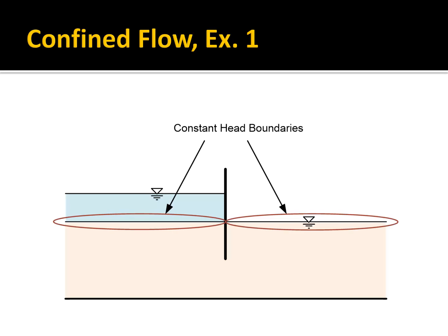In this case, we have 2 constant head boundaries. We would mark this in SEEP2D as a specified head boundary. There's a simple way to do that. We'd give it this head. You have to determine a datum. And for a problem like this, I would probably just pick the base down here as the datum. And so you'd assign a head value there, and then whatever your elevation is here, you'd assign as a constant head boundary. Everything else is a no-flow boundary.